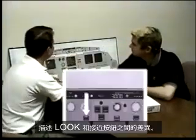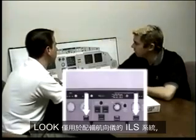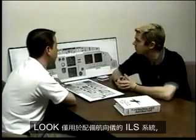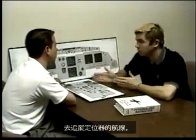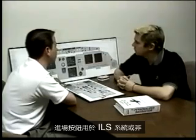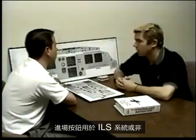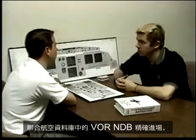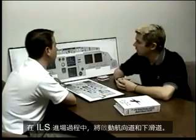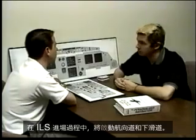Describe the difference between the loc and the approach push button. Okay, the loc is only used on an ILS system where the localizer is capable, and that's going to track the localizer course down. The approach button is used for an ILS system or for a non-precision approach for VOR or NDB in our database at United. The approach will, during an ILS, arm both the localizer and the glide slope.